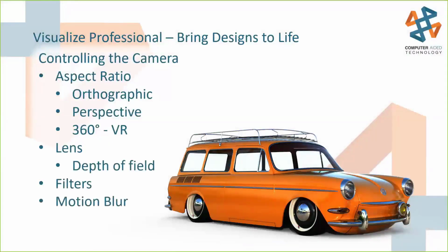All right, so we talked about controlling the different aspects of the camera. Of course, we can do orthographic views just like normal flat views inside of SOLIDWORKS, as well as perspective images to give us that nice vanishing point feel. We can also create 360-degree views for panoramas or for use inside of VR. We can adjust things like depth of field and motion blur with our lenses, and different filters for some pre-post processing effects. We can embed that into the rendering as it's created, so it shortens the amount of time needed to touch up these photos afterwards, and motion blur for creating animations.